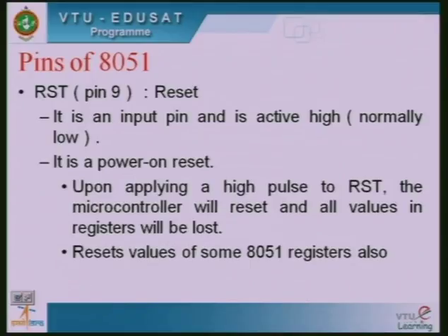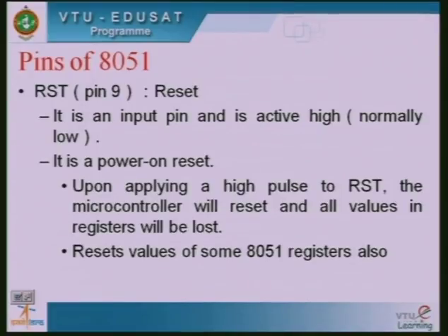The other pin which we should know of the 8051 is the reset pin. As the name indicates, it is an input pin and it is active high. It is normally a power on reset. That means, if we give a high value to this reset pin, the microcontroller will reset and all the values in the registers will be lost.